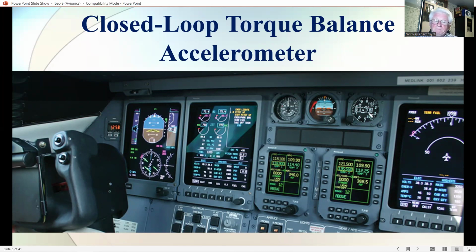The deflection of the pendulum from its null position under an input acceleration is sensed by the position pick-off, and the pick-off signal after amplification and suitable dynamic compensation is used to control a precision torque motor to maintain the pendulum at or very near to its null position.